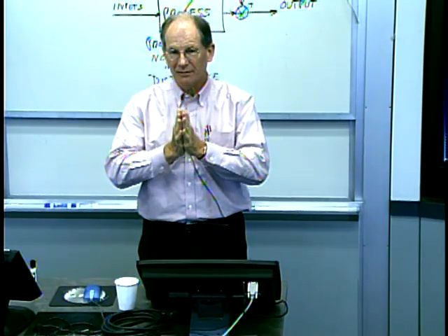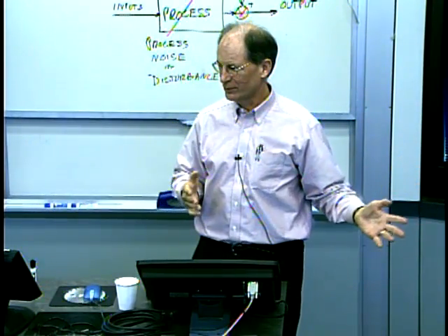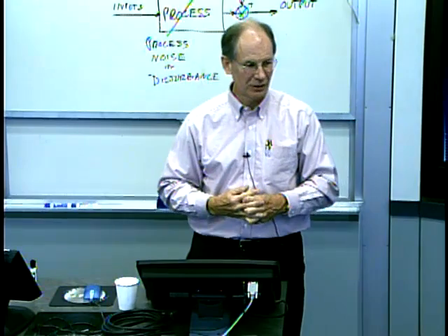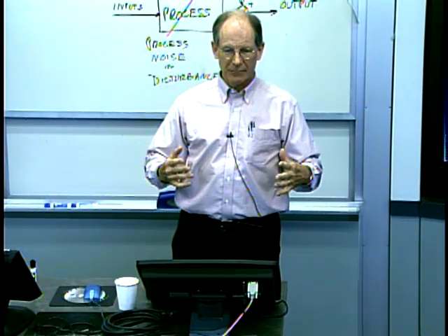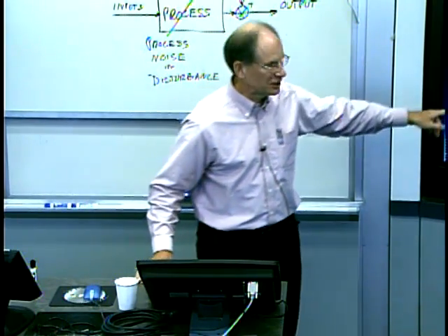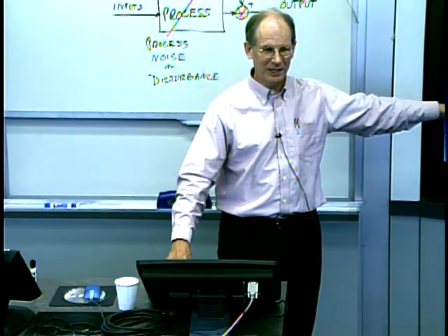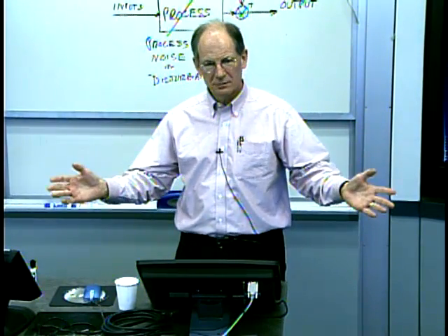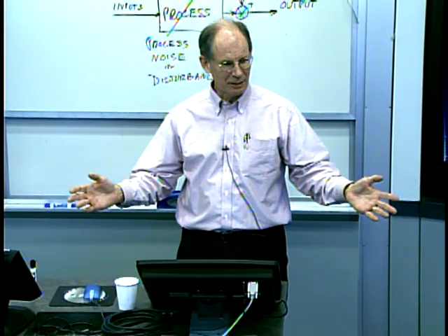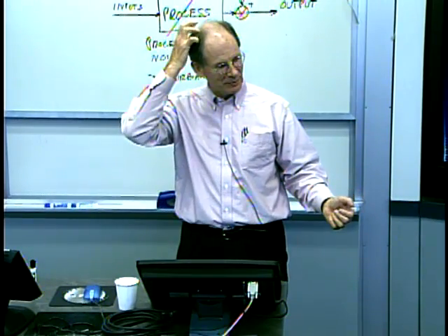But the last one that I was thinking of is you go out and buy a new process. Okay? If this is inherent in the process, and that's the best that it can do, then you sort of invent a new process, if you will, or you do things a different way that gives you a higher degree of precision. So you can take all these steps, but in effect, as you'll see, this is the cheapest, the easiest, and the first one you always do. You never make a decision about what to do until the process is in the state of statistical control. Why is that? Why am I so adamant about that? You never go to the next step until we've done this. Any of these things we've talked about.